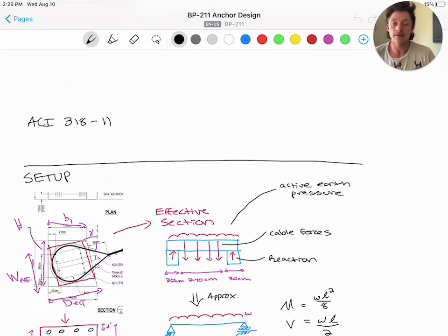We'll use chapters 7 through 10 to guide a lecture on placing and detailing of the reinforcement, general considerations for analysis and design, strength and serviceability requirements. Then, we'll use the code to guide additional stability checks performed in this section from chapters 10, 11, and 22, which will be flexural capacity of the reinforced concrete section under full cable forces, shear capacity of the reinforced concrete section under full cable forces, and cable bearing on structural concrete.